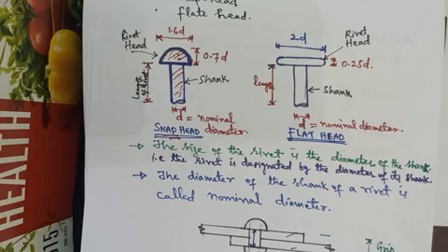Similarly, we have higher installation costs in case of rivets. There is also the necessity of preheating the rivets prior to driving. That is one of the disadvantages. Also, a high level of noise is produced during the riveting process, which is very undesirable. Skilled labor is necessary for inspection of rivet connections, and there is also a very high labor cost involved in case of riveted connections.